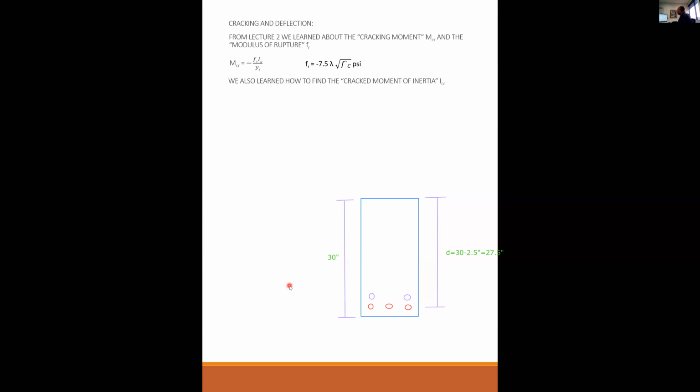But if I didn't tell you what size bar to use, then you could just go, instead of 5 number 10s, try 6 number 9s. And that would even it out as well. Right. Okay, that makes sense. Okay, thank you.